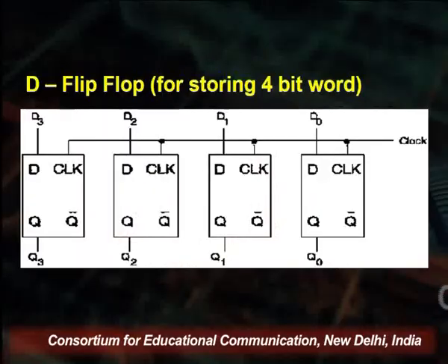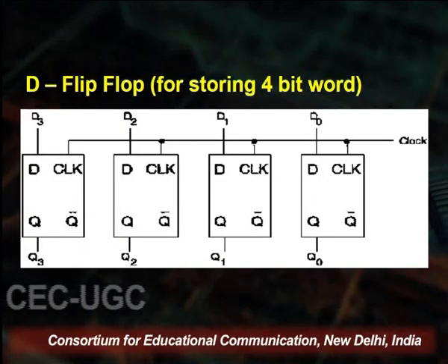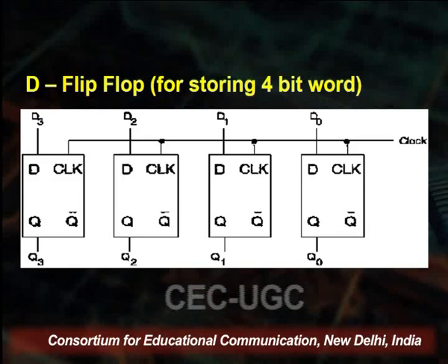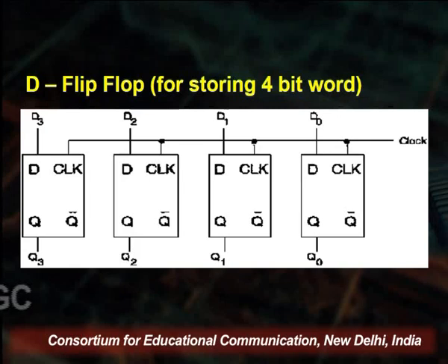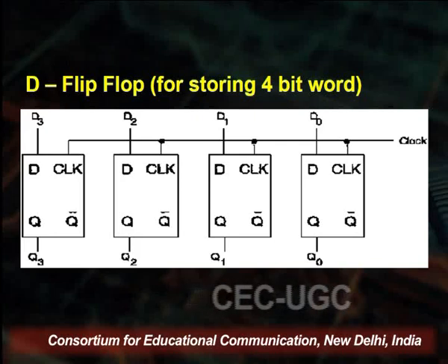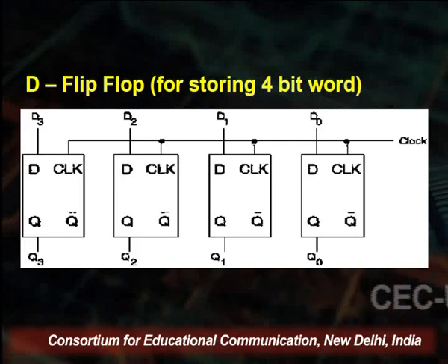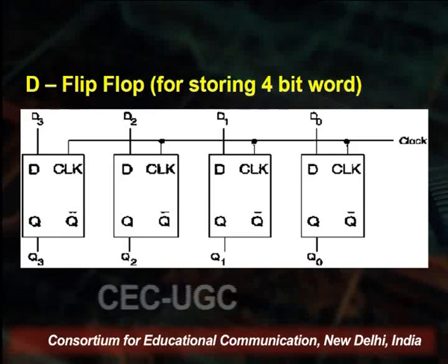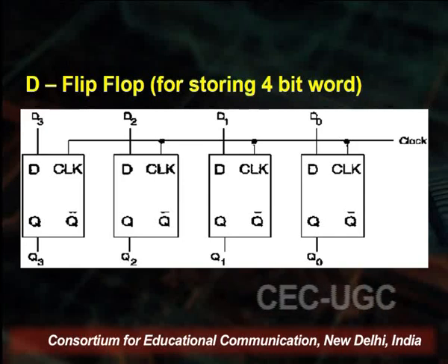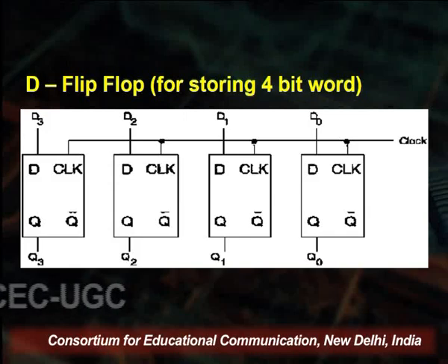So this way we can actually see storage of a word, which in digital terminology is 4 bits together, in flip-flops. As we can see, we have 4 D flip-flops, and the D flip-flops have all their clocks connected with one another and also to the main circuit with the clock input. That simply says that all the D flip-flops will be working at the same point of time when the clock is high.